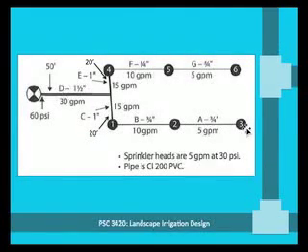For this example, the sprinklers are spaced 40 feet apart, and section D of the pipe right here, I'm giving you that information, is 50 feet long. Sections C here and E here are 20 feet long. And then you'll just use the same kind of table setup for this as we have in the past 2 examples. So the question is, what is the dynamic pressure at sprinkler number 3?